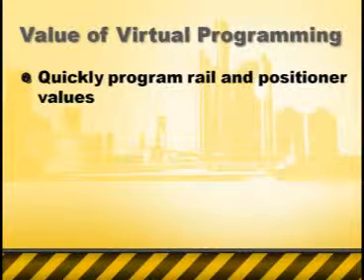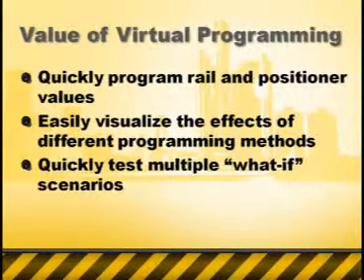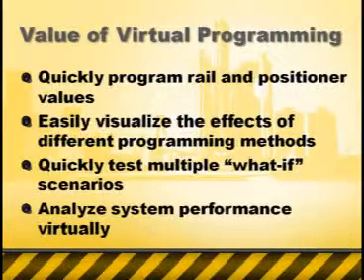Okay. Well, we saw how easy it is to program the rail and positioner. This saves a lot of time for the programmer, especially when there's multiple weld paths. Since we're working in a 3D environment, we can examine the effects of different programming methods. We can visualize different production scenarios, and we can see their effects on the work cell cycle time. This really increases the engineering quality when developing a work cell.